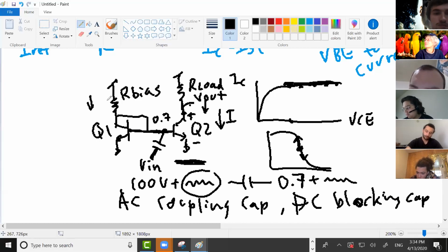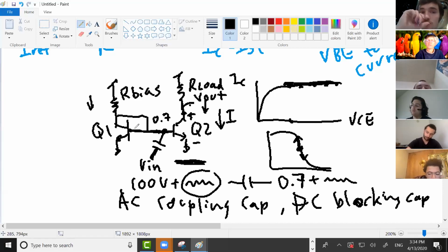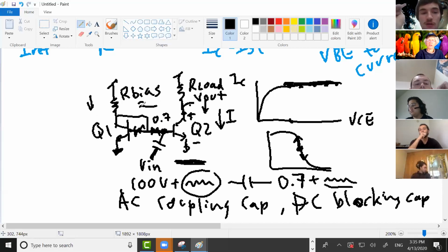It's a DC source. It doesn't like having moving signals introduced to it, and that's what this does. This is directly introducing a moving signal. So you'll see next week or the week after, you'll add resistors here to protect the left side of your circuit. So this moving signal right here doesn't go that way. It only goes into your amplifier.